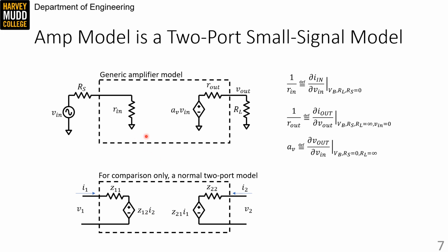by making sure that RL is typical for an amplifier when we measure Rin, and Rs is typical for an amplifier when we measure Rout. Because that way the values for Rin and Rout that we get will be reflective of any secret feedback that's inside the amplifier during standard operation. So our model presumes Z12 is 0, so we don't model any feedback to the input. That means we need to take very careful care with making sure that we measure with the proper RL and Rs.